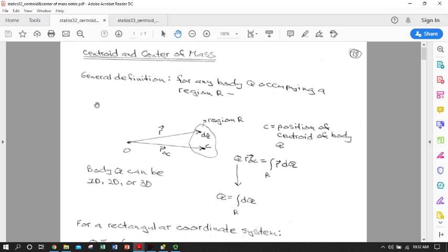So the gravitational forces acting on the mass on either side of that balance point are the same, and so the object would stay balanced on a single point. And so we will have a centroid and a center of mass, which we can define for each orthogonal direction. So you'll have an x centroid, a y centroid, a z centroid, and of course the same thing for the corresponding center of mass when we roll in our density function.